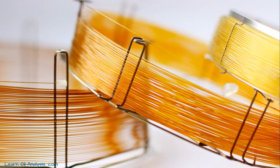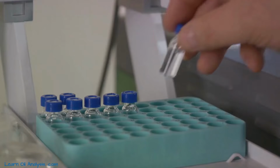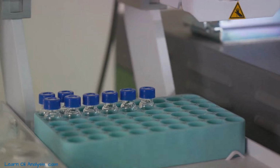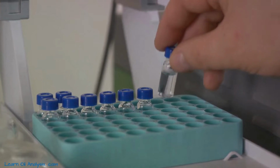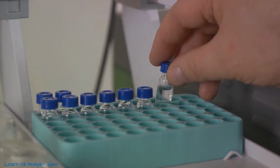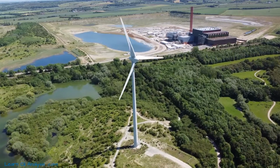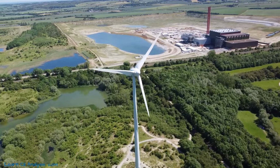Seeing a rise in carbon monoxide levels is a call to action. It's time to check your insulation for any signs of wear and tear, and perhaps add a Furans analysis to your transformer oil sample to both confirm paper breakdown and identify the way it's breaking down. It's quite fascinating, isn't it? By monitoring these key gases, we can diagnose potential issues in a transformer before they escalate into major problems.